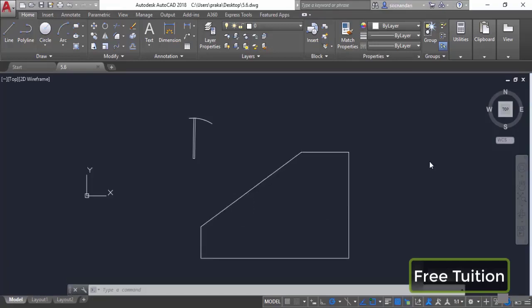In this video, I will tell you about the align command of AutoCAD, and using the align command, you can move an object and also align its geometry according to your requirement. Now in this case, we have this simple geometry here, and we have this door block. Now let's say that we want to move this door block on this part of the geometry, and we want to move it in such a way that it completely aligns with this wall or this geometry, and it also remains inside this geometry.